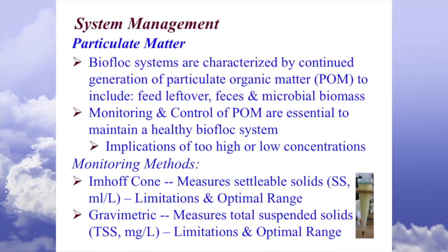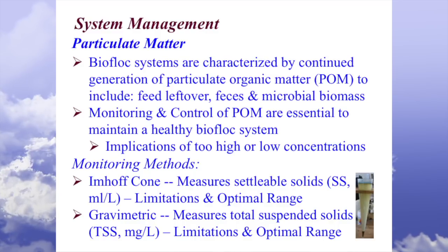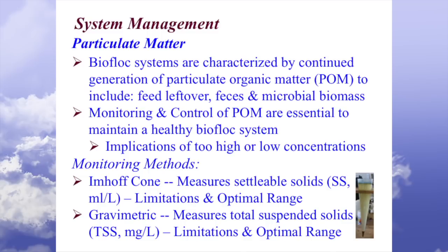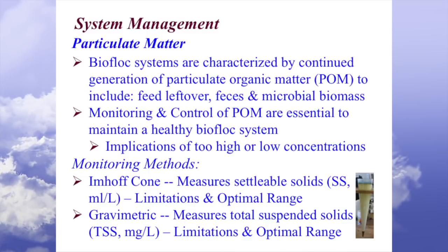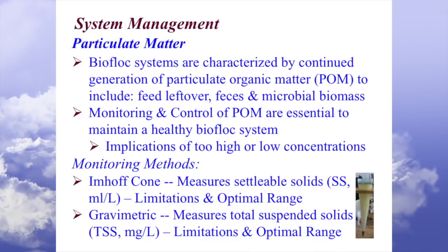Biofloc systems are characterized by continuous generation of biofloc, of organic matter for the most part, and you need to maintain it. If you don't maintain it at an optimal level, this may affect the system performance, including the shrimp performance. Monitoring and control of particulate organic matter are essential to maintain the optimal condition. For the monitoring method, you can use the Imhoff cone.